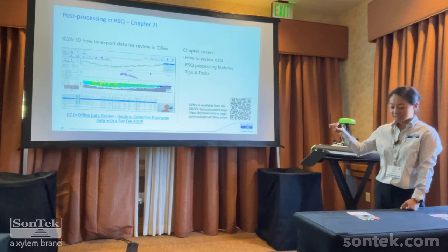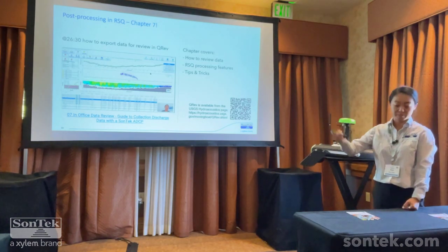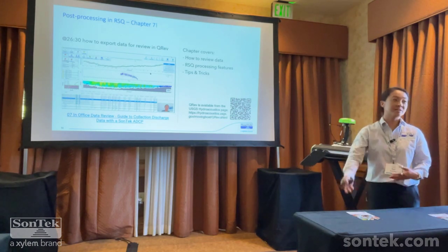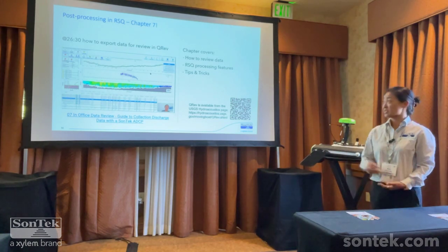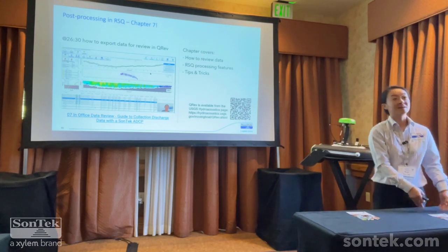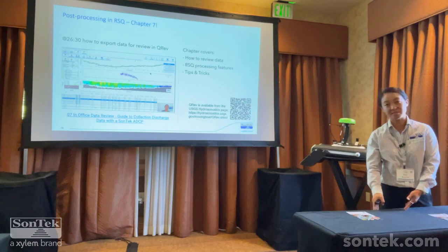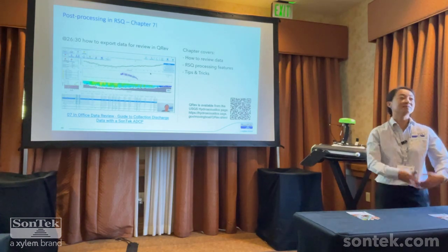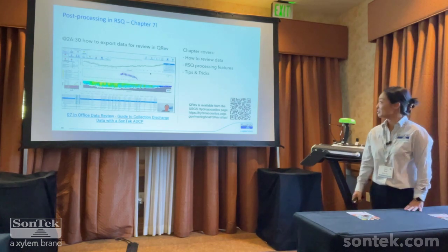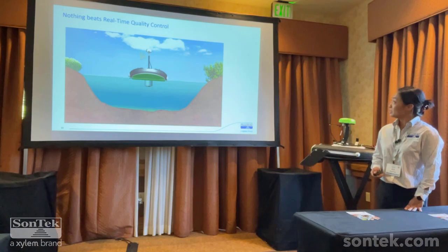In the video series, you will see a section where we explain how to take our data and put it into QRev. If you do end up having to do that, the USGS actually physically has to, before they leave the site, take our measurement from our software, put it into QRev, and make sure that it passes in QRev before they leave the site. So something to keep in mind.